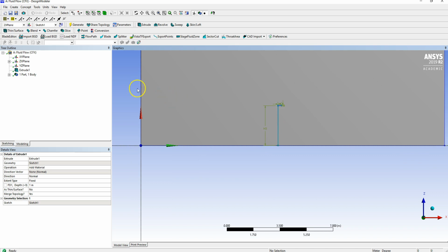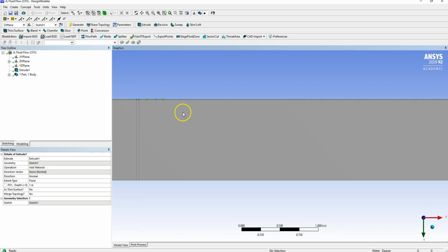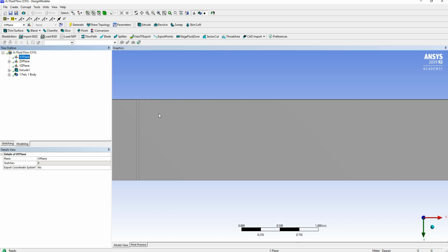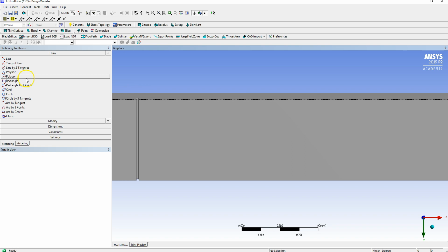So rain is going to be coming from left to right. It's going to be striking this building, and the flow is going to be causing it to recirculate. And what we're interested in is how wet this area underneath here becomes. So what I'm going to do is create a sketch on the bottom face of the domain. The reason I'm doing this is so we've got an area beneath the shelter where we can calculate the amount of rainfall that falls on it. So I'm just creating a sketch on the XY plane. So this is the plane that the shape sits on. And I'm just going to slightly rotate so I don't accidentally select the top face here.